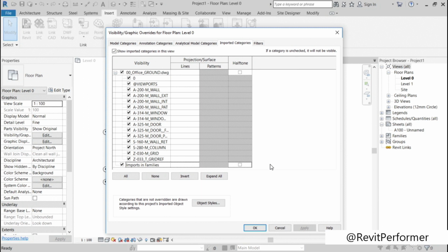Now, importantly, the one thing you'll notice is all of the layers here are adhering to the AutoCAD standard. And that was BS 1192, remember, from previous chapters. So basically, everything that's coming is adhering to the appropriate standard that you're working to in your Revit project. That's the whole idea. You make sure that your AutoCAD linked CAD drawings adhere to the same standard as the standard you're working to in Revit. So what we'll do as we go through this chapter is go through all of these settings and overrides and everything and work out how they work and see how they work in our Revit project.